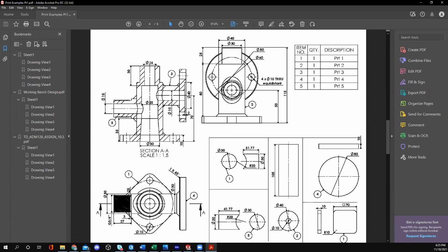So this print right here would be separate to what a welder would see. This would be somebody machining all these pieces, and then later a welder would come through and have a separate print with all of his call outs on where to set those certain dimensions of weld profiles and whatever design weld it is. Potentially either that, or it would say, though I'm looking at this, it does look like we have different size beads. I was going to say either that, or it would say all welds are 1/4 inch fillet welds unless otherwise noted, and then that could just be on this print.